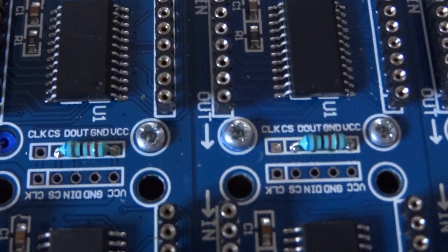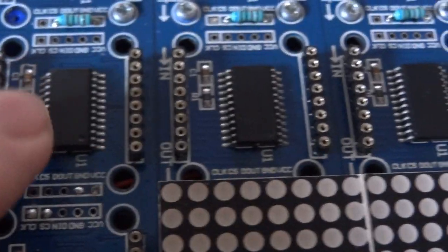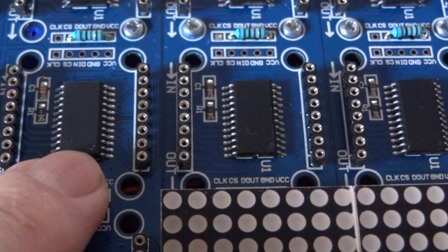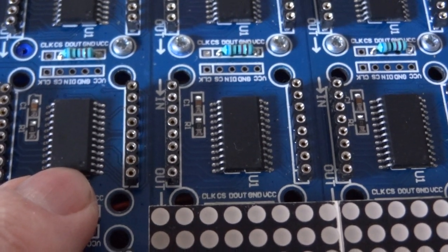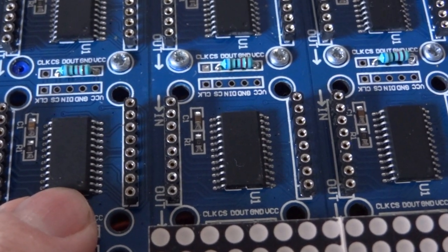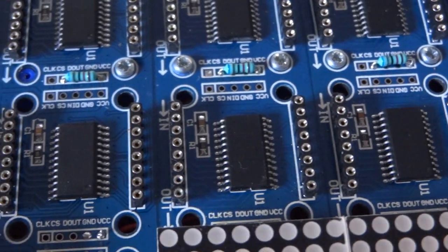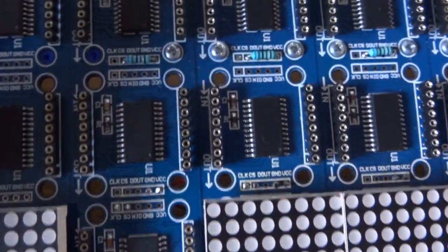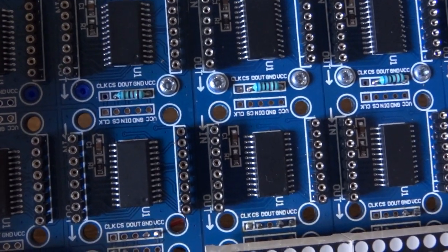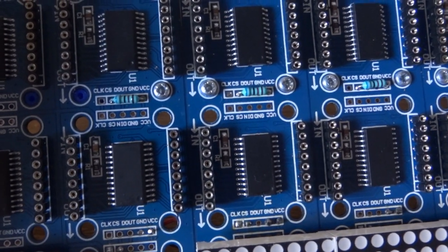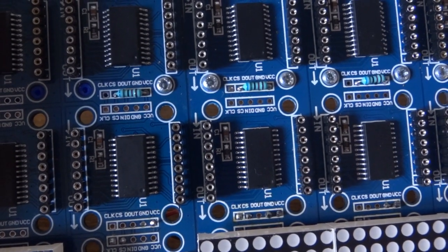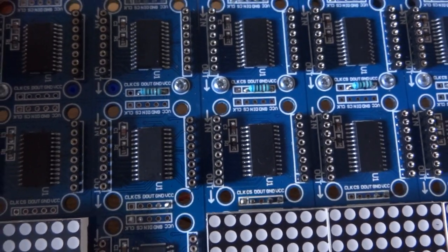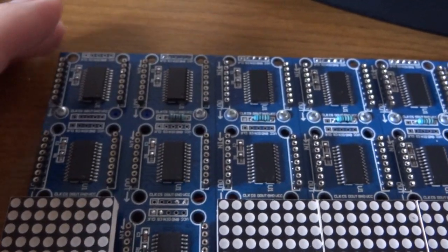Yeah. It stops the chips clocking rubbish into them during the power up stage, which, if the chips happen to go full brightness or self-test mode with all LEDs illuminated, it can draw too much current and overwhelm the power supply. So the idea of the resistors is it keeps the chip select line pulled up high, which is not selected until the microcontroller actually really wants to send data.